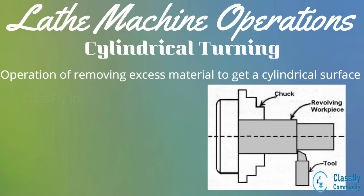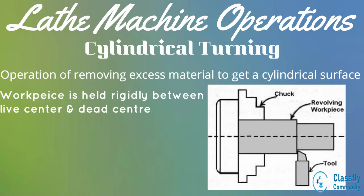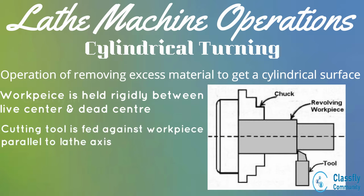Well, in operation, the workpiece is held rigidly and rotated between the two centers of the lathe. They are known as the live center and the dead center. Now, the cutting tool is fed against the revolving workpiece in a direction parallel to the lathe axis. Hence, material is removed longitudinally and we get a cylindrical surface.